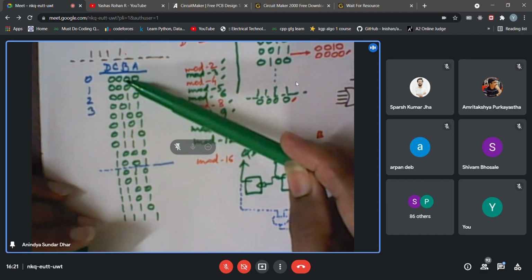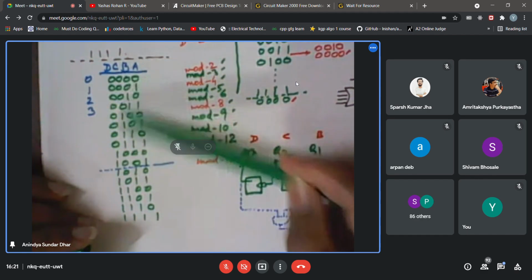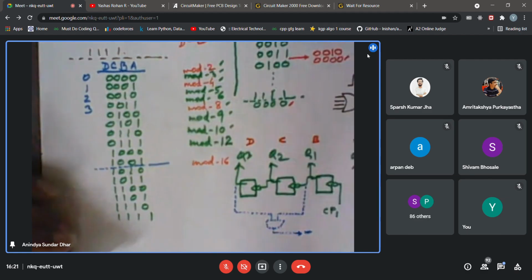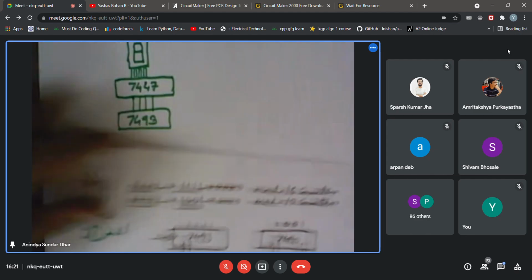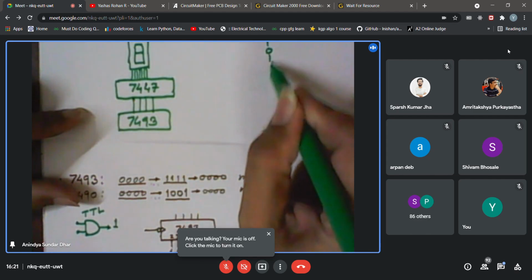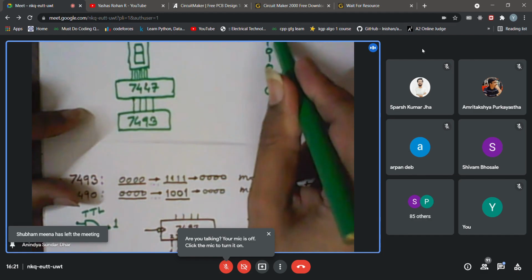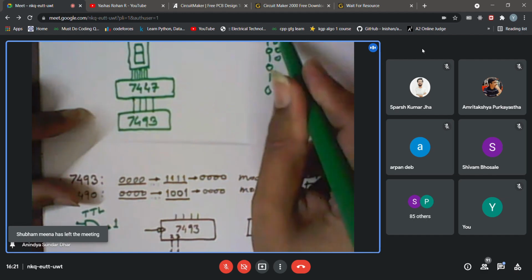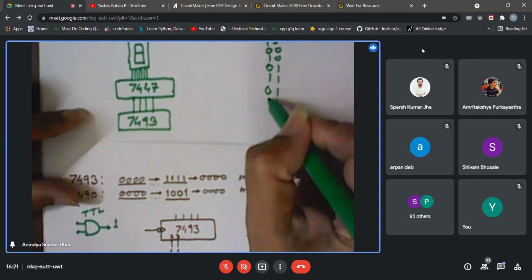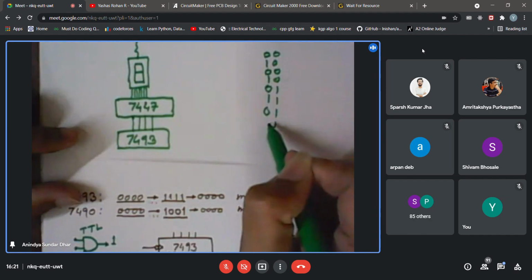Next bit is toggling at half the frequency, 0, 0, 1, 1, 0, 0, 1, 1, 0, 0, 1, 1. So if you write the outputs, what is your observation, then you may find that actually the third bit is giving you this type of 0, 1, 0, 1, 0, 1, whereas the second bit is actually keeping throughout 0, maybe for the first 4, then it is coming 1. So now you know that, okay, this is which bit, this is LSB. So then it gives you an easy way of exchanging that.